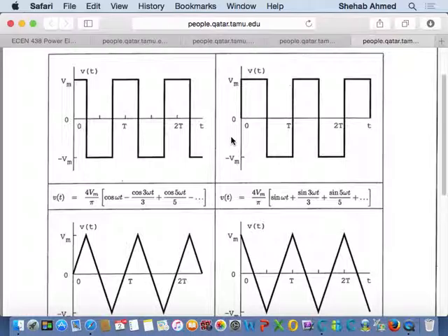As you know, we are going to be concerned with waveforms that are sinusoidal as well as non-sinusoidal. Non-sinusoidal waveforms, we said, will have a DC component, which is our average value, and then an AC component. To understand this AC component and design filters for it, I need to understand the harmonic content, or the frequency content, of that waveform. How do you do that? What's the mathematical tool? Fourier series. That's a mathematical tool that you've learned to use to do this kind of work.